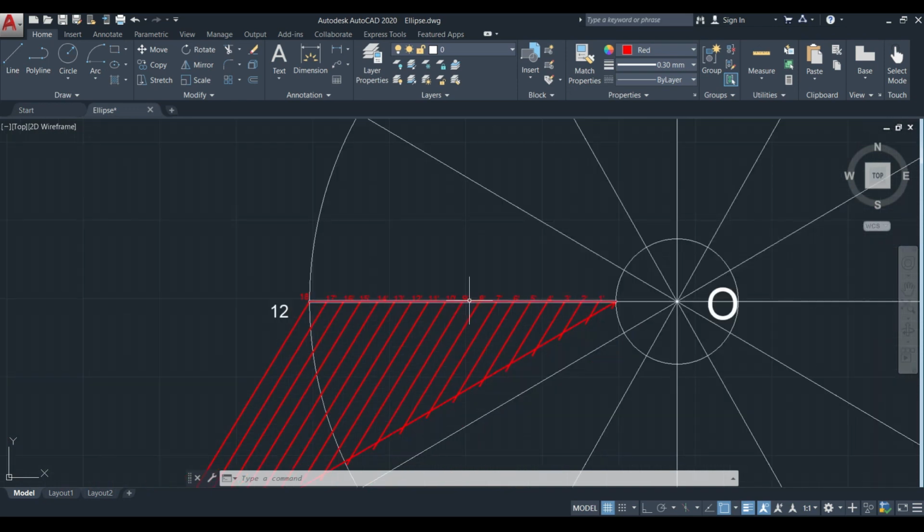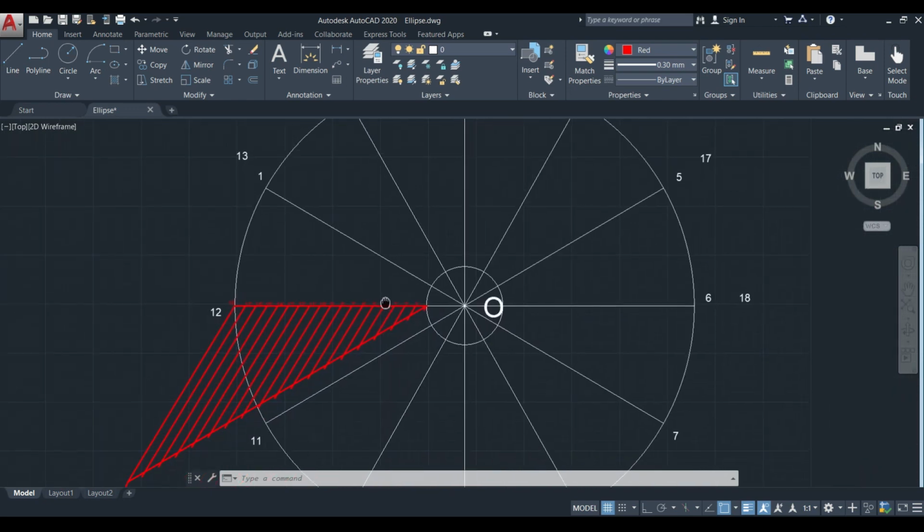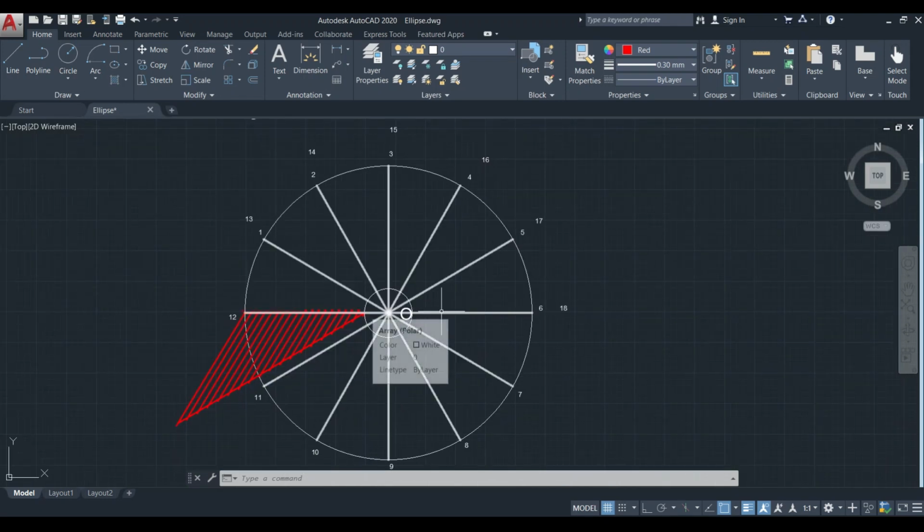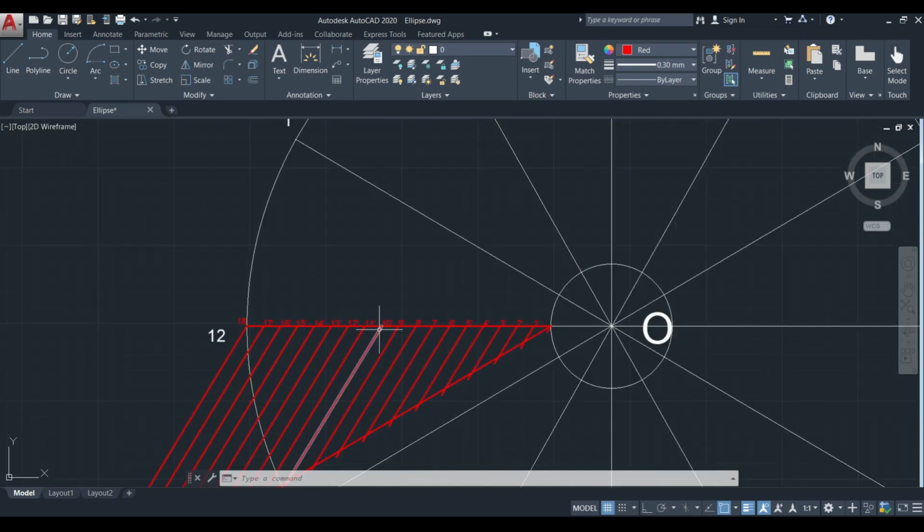So likewise, if it is asked to draw the Archimedean spiral of two convolutions, the straight line should be divided into 24 equal parts, because one convolution means 12 equal parts, then two convolutions means 24 equal parts. That you have to note.